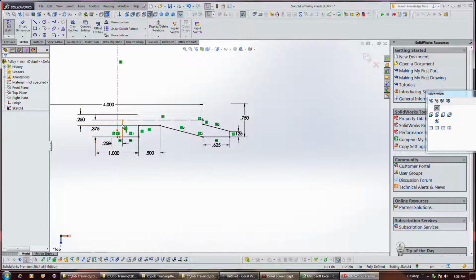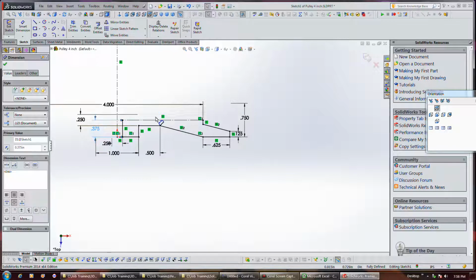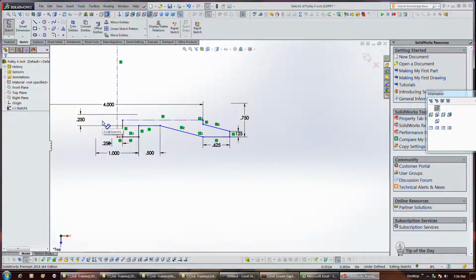Apparently, and I don't know why exactly he did this, but apparently he's defining all these diametral dimensions because, for one thing, you work with full thickness parts and specifications like a 1 inch hole, not half that. Usually lists the radii. But he's also about to mirror this whole thing over here so that it creates a closed profile. At any rate, I'm going to delete this 0.375.